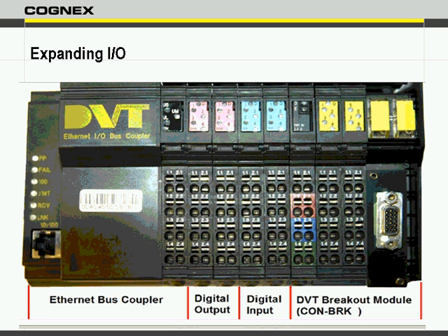So we take a look at these functions right here. Again, to view what script 1 and script 2 do, I don't need to look here. I can go over here to the virtual I/O function and go down here and take a look at where the scripts are. We have users and we have our scripts right here. So this is my digital output 49, which we'll talk about mapping in a second. We're looking at script 1 and script 2. They should go high when I trigger this, and they do go high for about a second, and then they cancel.